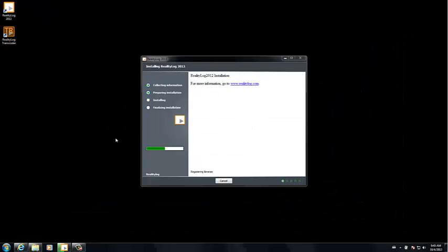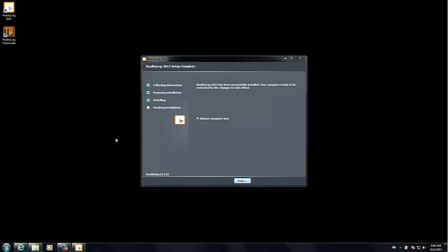During this process, you should not get any errors of any kind, not even informational messages. If you do, it would probably be if you have antivirus software installed or something like that, that's going to warn you about stuff happening on the machine. I would urge you to turn off any virus protection program before you do the setup.